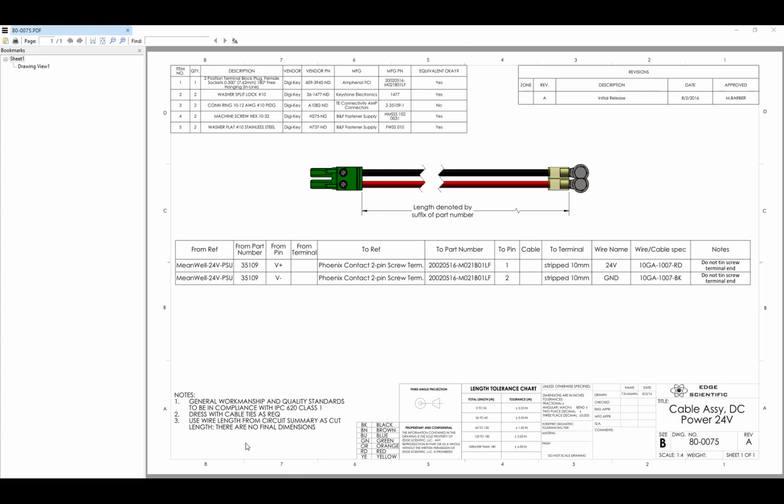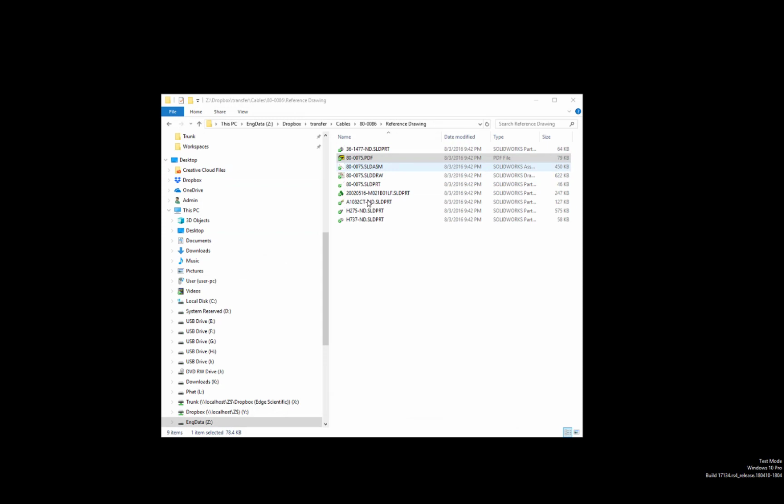Over here you've got all the notes, part number, description, from to, front view of the drawing with the length dimension, and then the bill of material, which should be generated automatically if you've got your assembly set up correctly. And then in the ref table, we're not checking anything into a revision control system, but we are just manually adding a revision, and I can show you how to do that. And then we've got all the SolidWorks related parts.